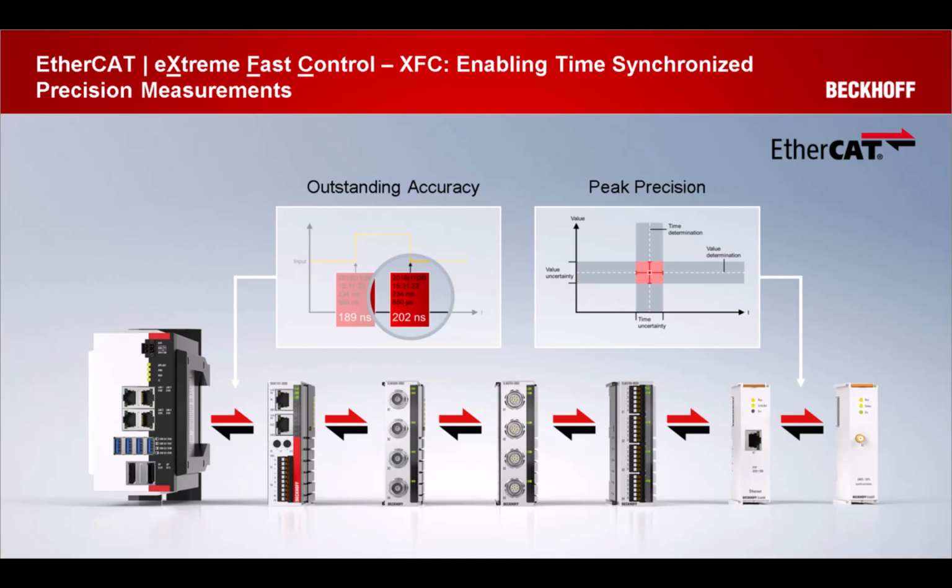And an extension of EtherCAT technology is Beckhoff's eXtreme Fast Control, or XFC, ensuring the measurements taken are not only very fast, but quite precise, down to the nanosecond between multiple devices. The two XFC concepts which will help you achieve time-critical measurements are distributed clocks and oversampling.